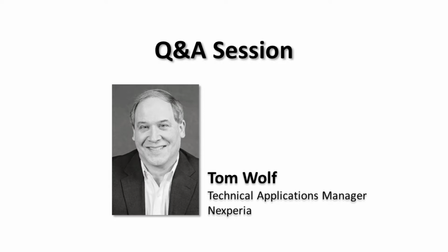Our handbook does have some examples on how to use our parts in a more off-on, as opposed to a PWM, application. So again, look at the guide for that, and I think you'll find there are some solutions that let you run in that. We also have some new parts we're developing which have even more extended SOA operating range. Essentially, taking a MOSFET and increasing that linear range so wide that you can basically treat it like a transistor. It becomes an analog MOSFET. So look at some of our newer parts, and you may find a part that fits that specific application.